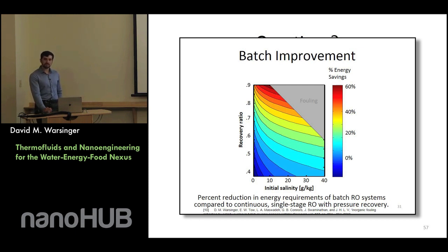My other question is, the membrane you are developing, is it just for desalination? You cannot use it for elimination of other biological contaminants? So the inverse opal membranes are largely for chemical and biological contaminants, and their pore size. The desalination membrane pore sizes for reverse osmosis are a fraction of 1 nanometer, whereas our other pore sizes for these larger scale contaminants like viruses and bacteria are, let's say, 30 to 1,000 nanometers in size. So we're doing a wide range of separations. We're also doing some water vapor from gas separations.